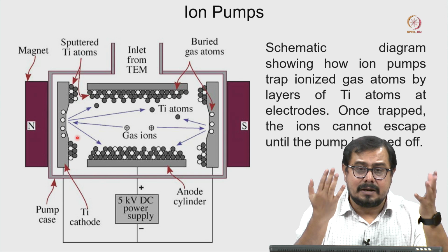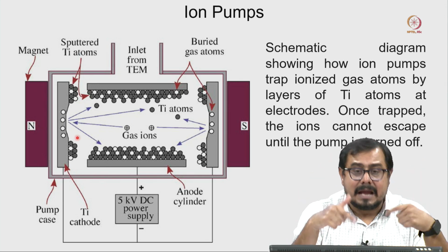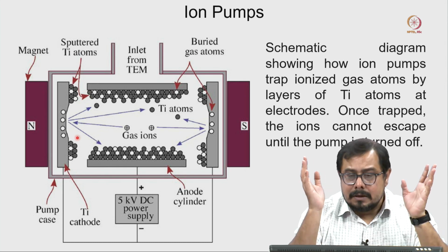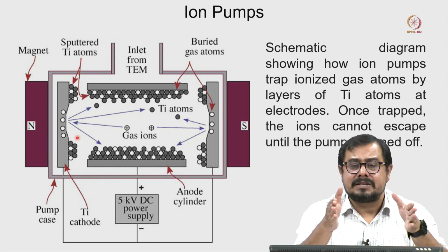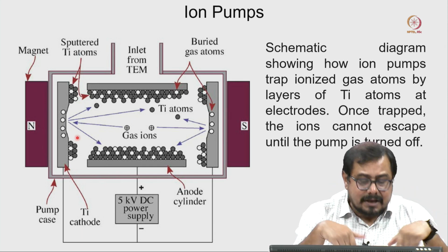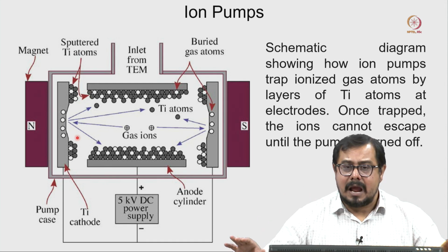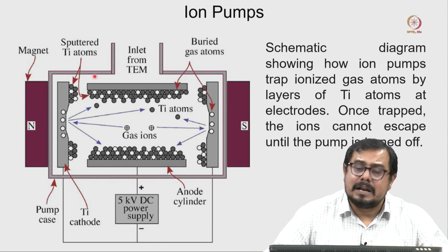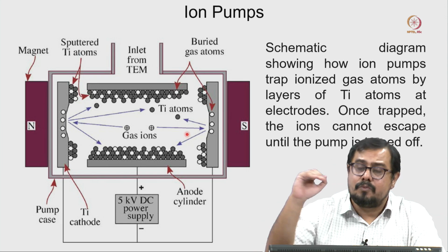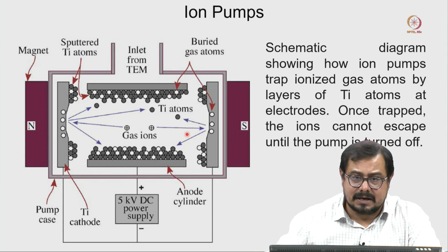Now, we want an ultra high vacuum, or a very good vacuum for the gun, and at that time the ion pump will start. If forcefully in our lab there is a microscope crash and I forcefully start the ion pump from the beginning, it is going to exhaust the ion pump completely, the entire ion pump will be damaged, and that will be very expensive. That is one of the reasons we cannot start the ion pump at the beginning. We have to wait a little bit and then we can start it.